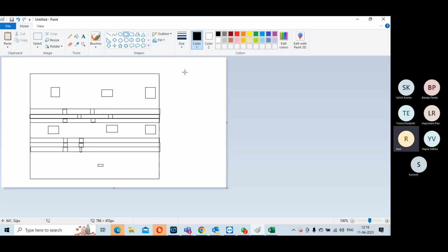Isolation is required for the logic which is going out from the shut down domain to the always on domain, like the interface between the blocks which are shut down and always on. Pass the information clearly, even if suddenly an off condition is there. Isolation cell won't give the power to the off domain. Isolation cell will always be placed in the block which has an off domain, but connected to always on cells.